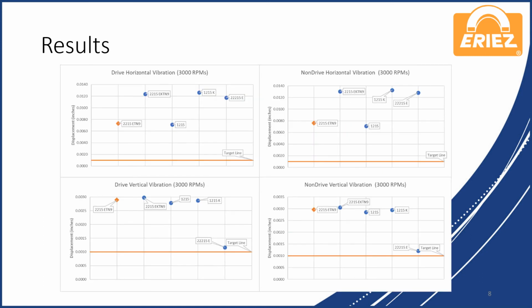Shown here are the results of the FEA harmonic analysis for each location of a bearing in both directions. Note that the matching force used to derive the displacement force is in the non-drive direction on the vertical side, which could cause numerical error on the other locations in terms of magnitude. However, the reduction will remain constant.